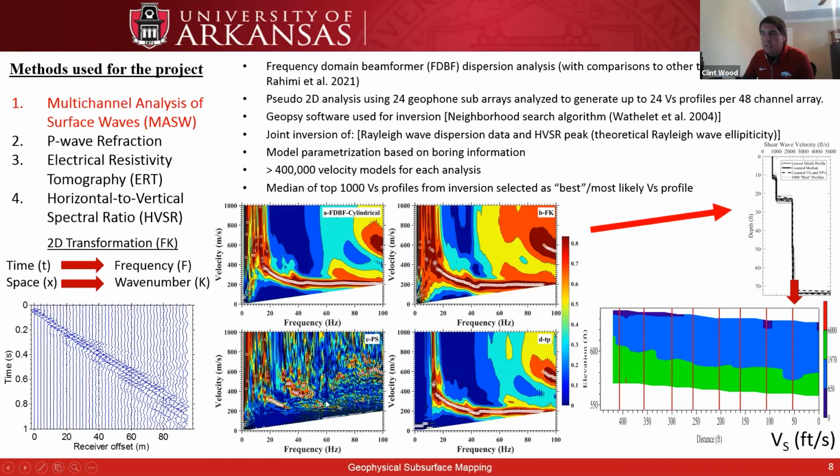And in this particular location, and we've seen it at other shallow bedrock sites, phase shift does not perform as well as other methods. And that's unfortunate because it's used in a lot of software out there. So that's one thing to note. If you end up using this MASW a lot and you get poor dispersion information, you may try a different transformation method, and it may significantly improve your data quality, especially at these shallow bedrock sites. At soft and normally dispersive sites, it doesn't really make any difference which one you use. They all give about the same result. But it's these challenging, complex sites that really cause problems in surface wave testing.